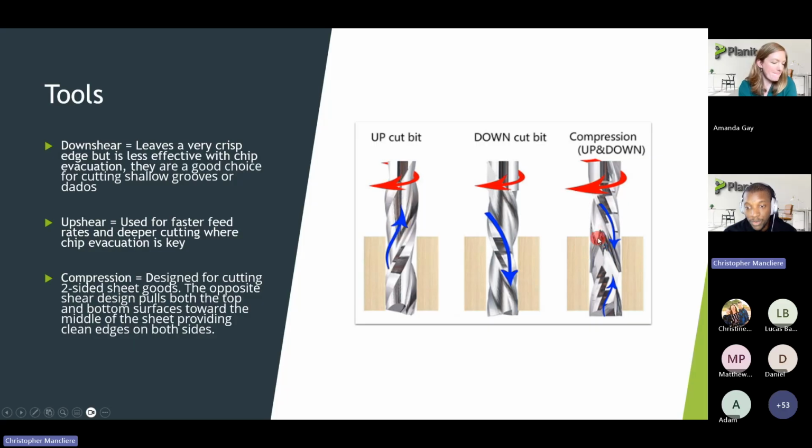When you use this, it's really designed to create outline cuts. So you cut through your part with a good finish, where you minimize the chip on the face, but also minimize the chip on the back of the part. And because at the bottom of the profile you're pulling up, it will also help to evacuate and preserve the back of your part as well. So this is really designed for doing outlines.